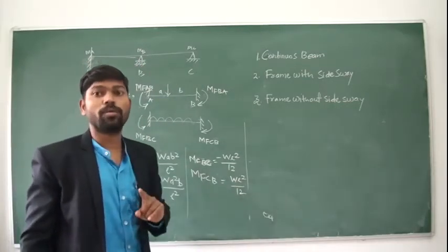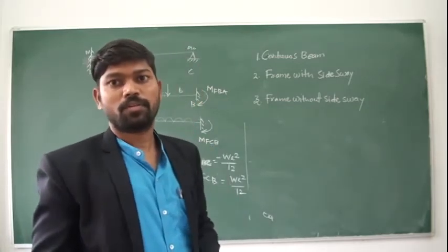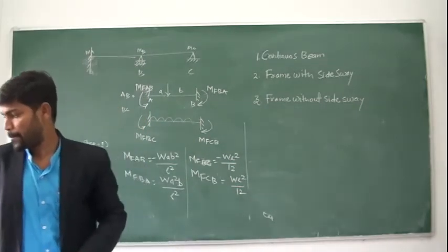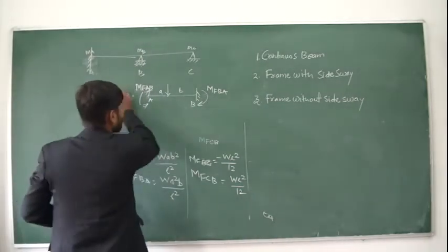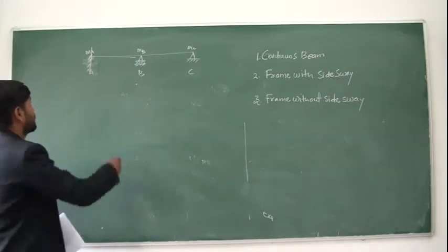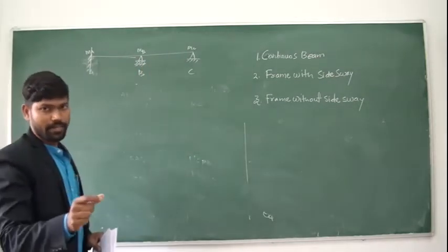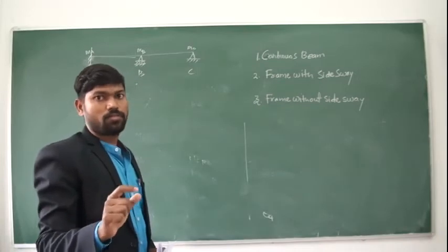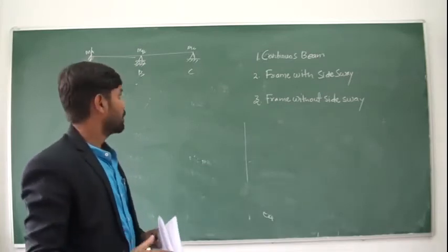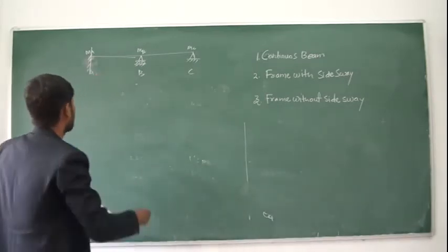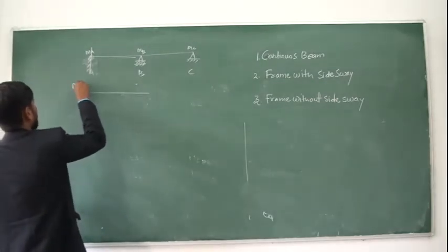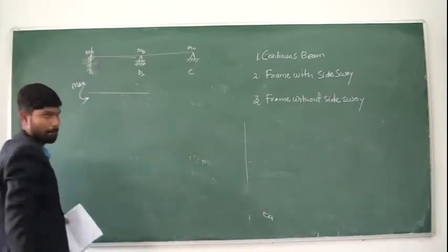So for that, slope deflection equations are there. Okay. Now these equations, see. Now this MA, MB and MC I will write differently, in different forms from what we have already written in the three moment theorem, that was different. So here I will write this MA as MAB.